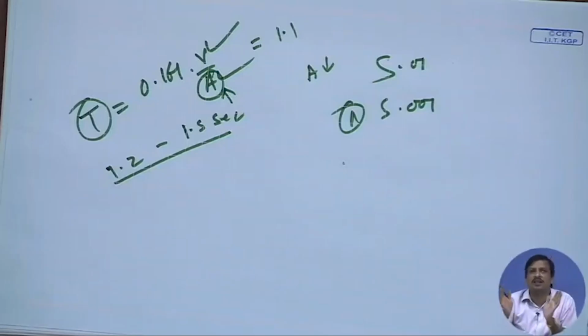So, when you do a design of an auditorium, two things. One is that you give consultancy to the architectural engineer that I require this kind of shape, because if the shape is not this kind, then the auditorium acoustics will not be good. I require this kind of seat arrangement, I require this kind of ceiling volume, this minimum volume should be this, I require this kind of ceiling arrangement, this kind of ramping and this kind of seat arrangement, all things you can give that suggestion. These are desired for good acoustics. Then you know the surface area, then design is done.